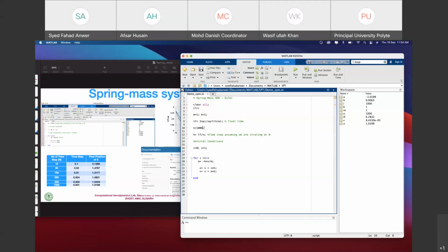So that is the whole reason why the Euler time stepping is not an ideal time stepping. It's only first order accurate in time. So we should use better ways like Runge-Kutta and all those things. So let us put back the 10 value, for demonstration purposes. It is easy to use the 10 value.